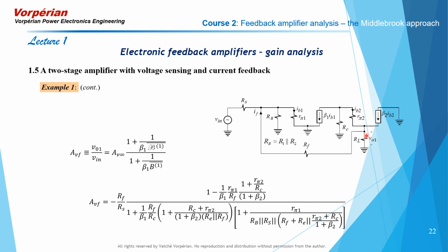And the beauty of all this is that it all comes out naturally out of the feedback formula given by the extra element theorem for the gain of the amplifying element. And you get the result like this, in very meaningful form.